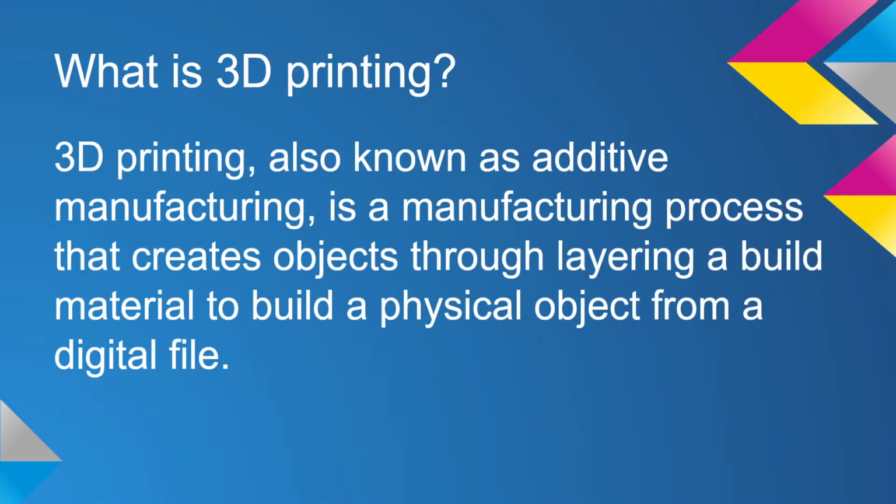So essentially, the 3D printing that we're going to be talking about uses a filament. This is PLA. It's 1.75 millimeters in diameter, so kind of like a weed whacker line, though a little more brittle than that. We run it through a portion of the machine called an extruder, which is just a motor that runs it forward and back. From there, the extruder feeds it into a hot end.